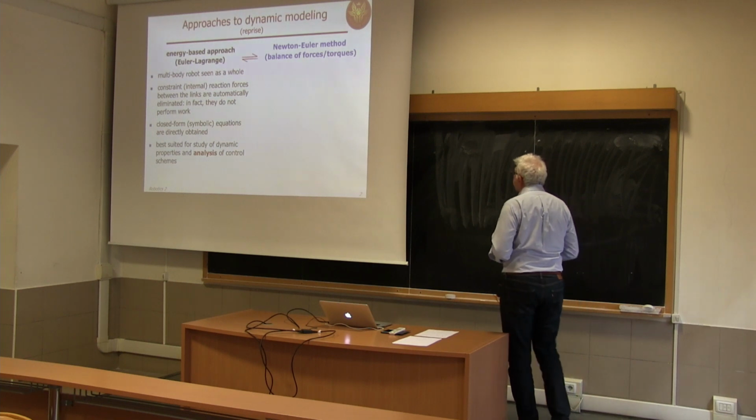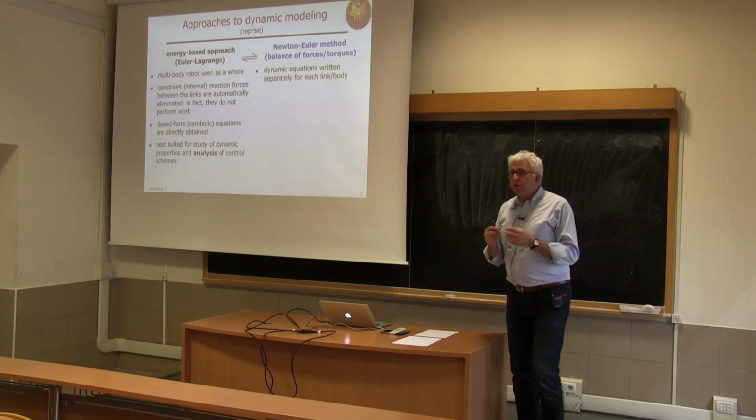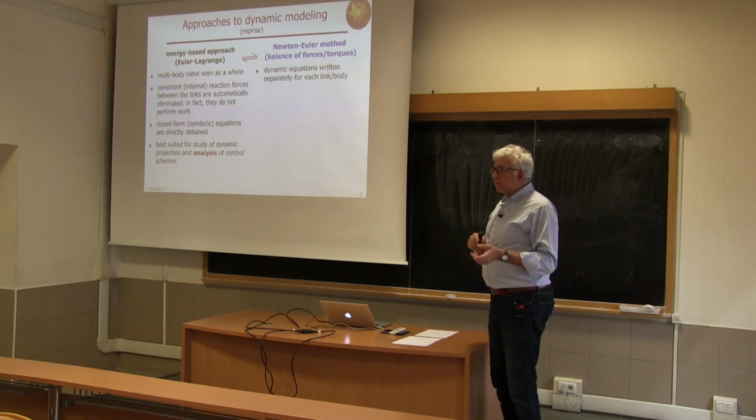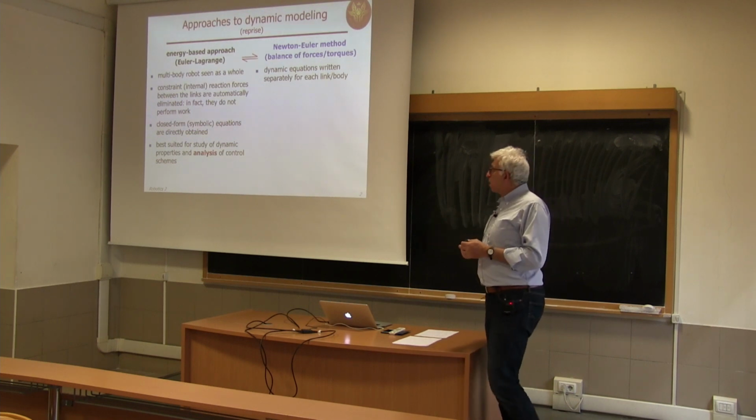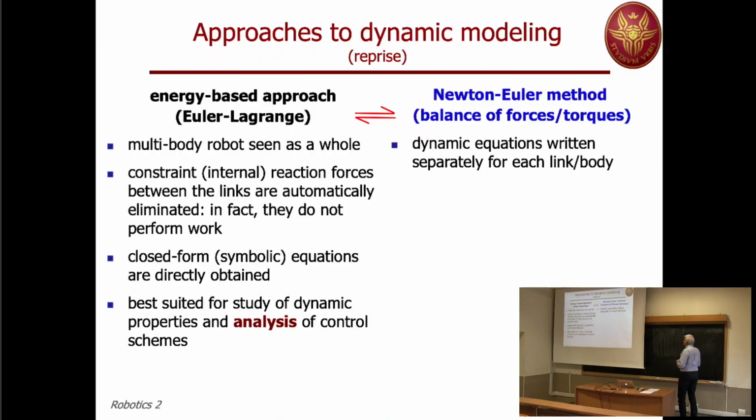Anyway, we balance forces and torques with their effect. And we do this for each couple of connecting links, so link i with link i plus 1, and so on, from the base to the tip. So we write several dynamic equations that balance forces and torques.